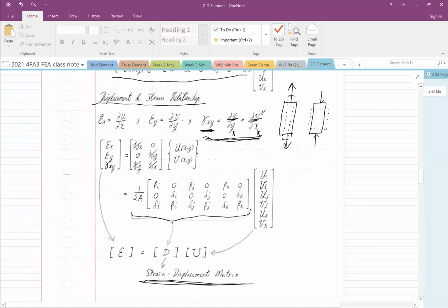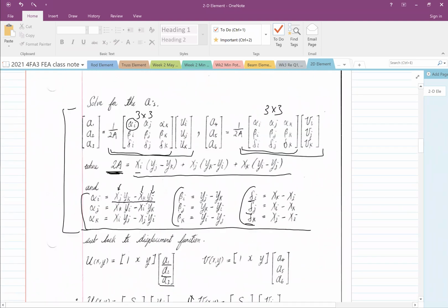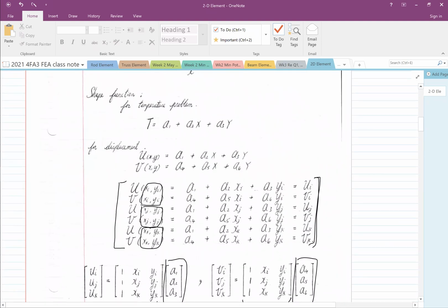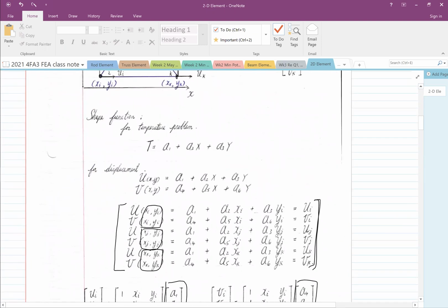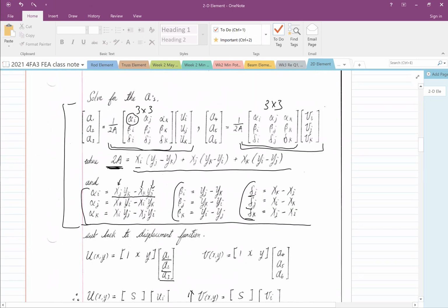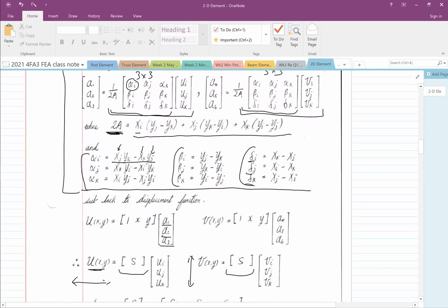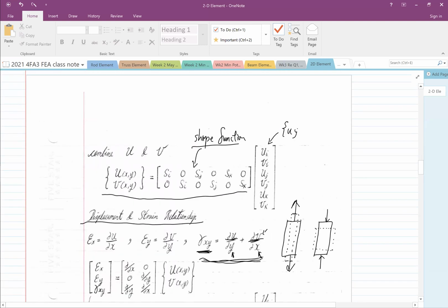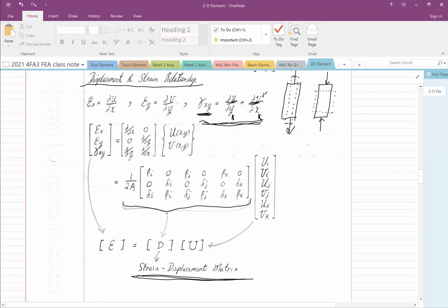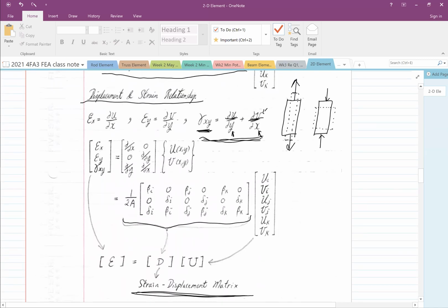Any questions so far? So what we did, we defined the elements with 3 coordinates. We developed the shape function painfully, many terms, many calculations. So we need an Excel spreadsheet, some program, computers to help us. We have the shape function, and then we take the derivative of that. I forgot how many times. Then we have a 3x6 matrix, which is a strain displacement matrix.